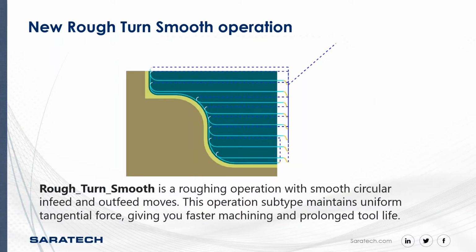And for the turning, they've added a new rough turn smooth operation. And you can tell by the curves, the yellow engage and the white retracts. It smooths everything out for a more constant force and constant chip load for better tool life.